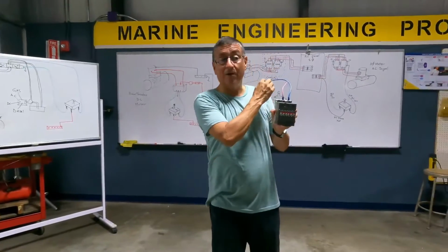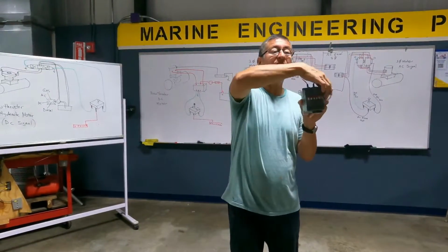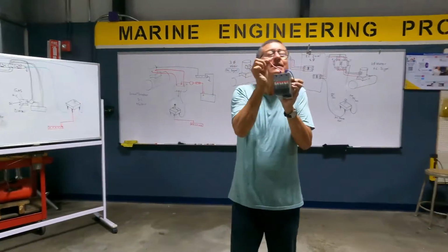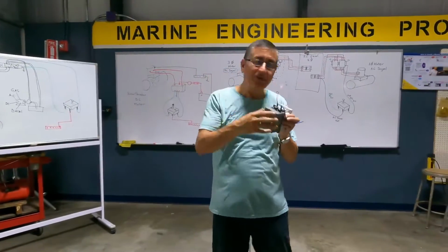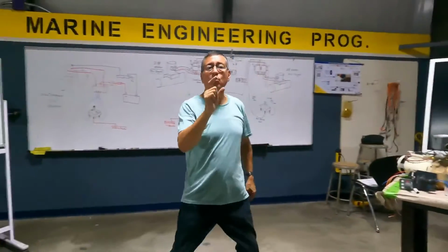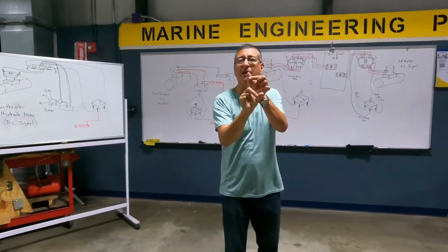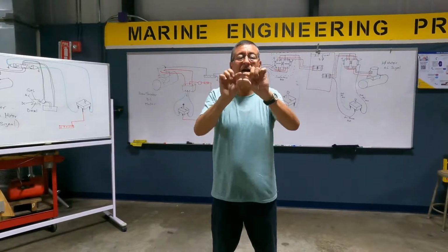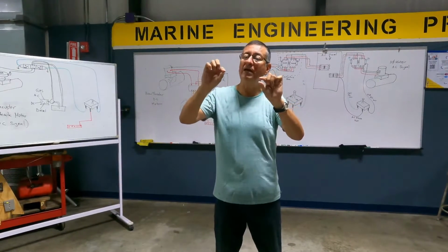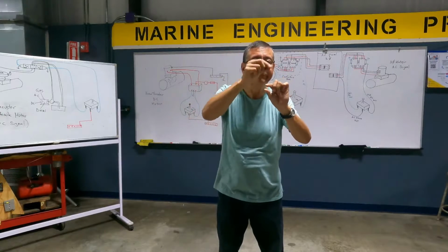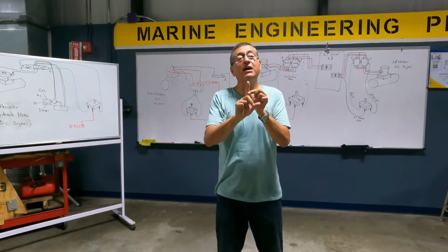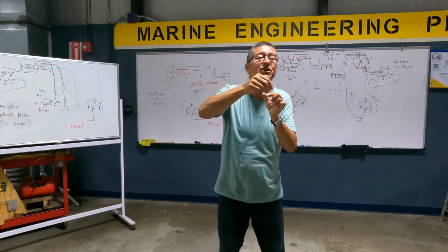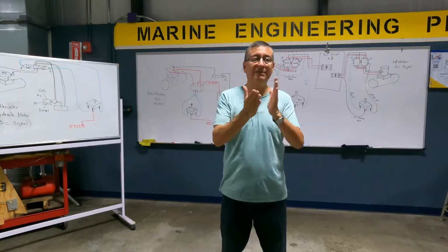This one, now I am going to explain, is coming from one of the hots. This is neutral and this is hot. But why does this cable have fewer amps? You remember? What happens if I have a bus bar with a heavy cable, 2/0, carrying 200 amps, and it enters a bus bar, and from the bus bar I have 3 cables, number 8? The 200 amps are now divided in 3, about 60 amps each one. That's exactly the situation.